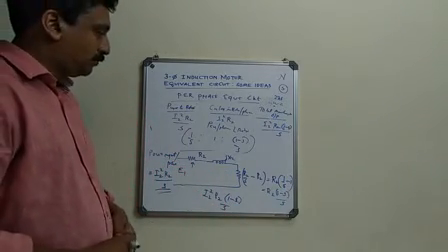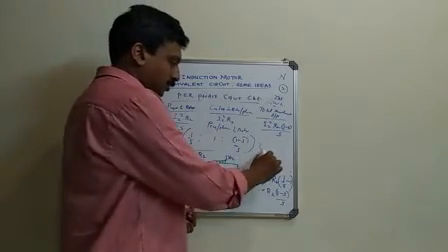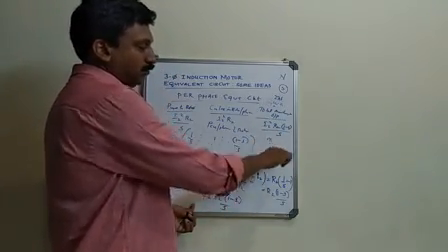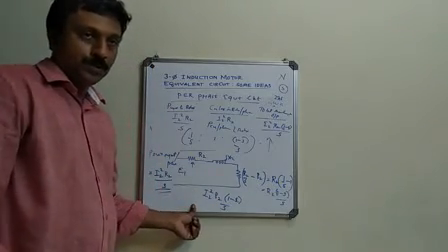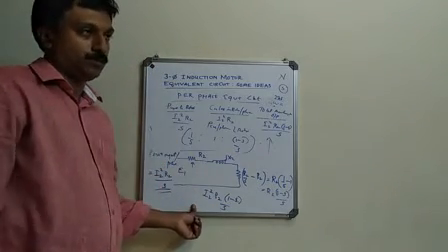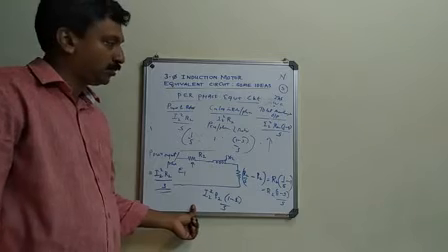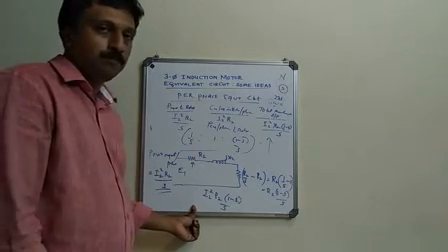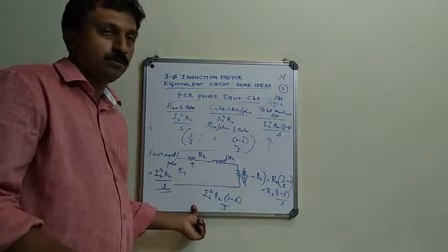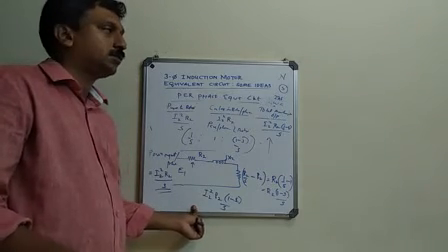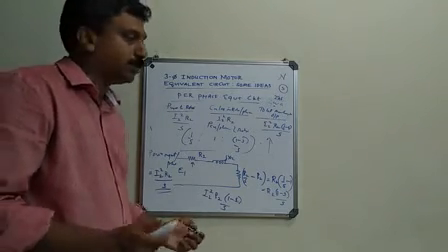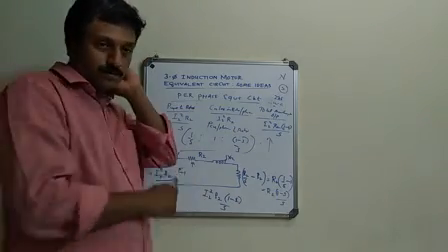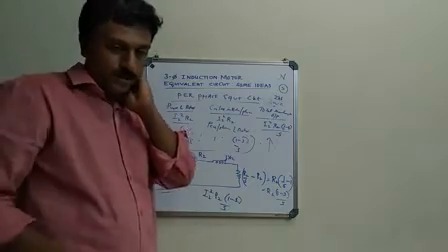From that, if you know the rotational losses, you subtract them and get the mechanical power output. You know the speed of the machine, and slip will be given. Then with T omega, omega being 2 pi N by 60, you can easily find T.